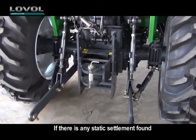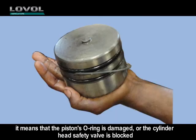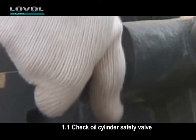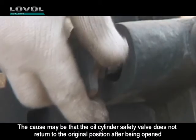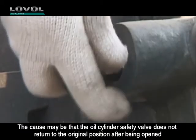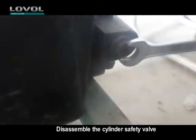If any static settlement is found, it means that the piston's O-ring is damaged, or the cylinder head safety valve is blocked. 1.1 Check oil cylinder safety valve. The cause may be that the oil cylinder safety valve does not return to the original position after being opened.